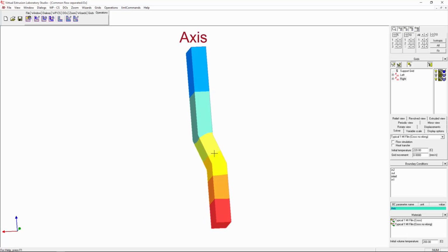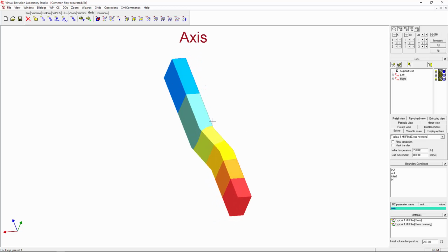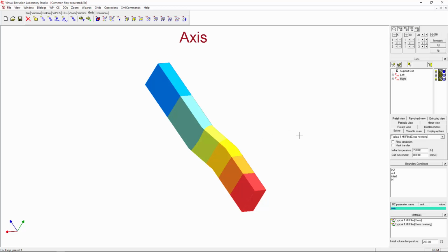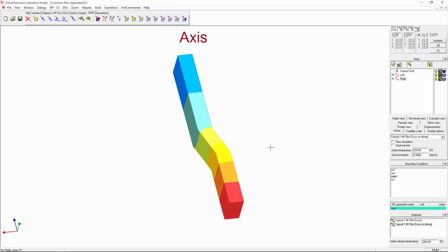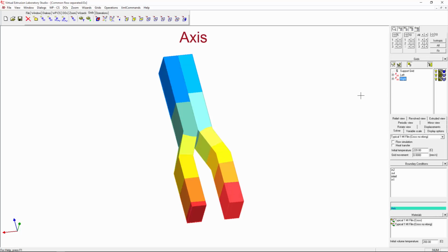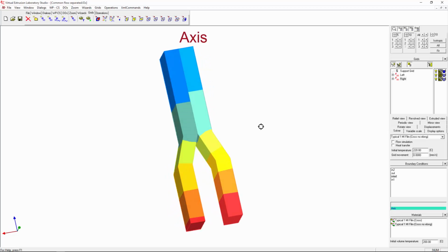Basically, these two geometries will be solved independently, so there won't be any difference if you multi-select them and run them together, or if you select one, solve it, and then run the other one and solve it. Why? Because these nodes are completely independent. They are not connected. There are no shared degrees of freedom for velocity, pressure, temperature. They're simply separate for these two meshes. Well, this kind of solution gives us, of course, non-consistent pressures, and also it will give us non-consistent velocities.